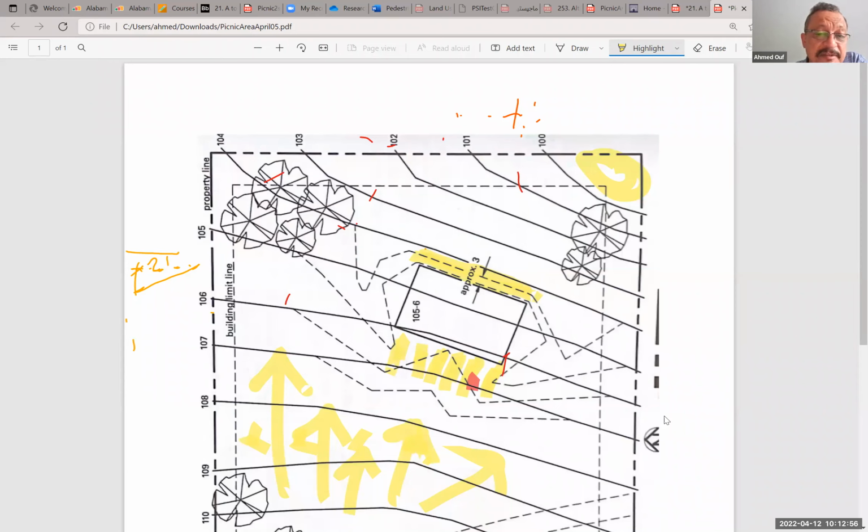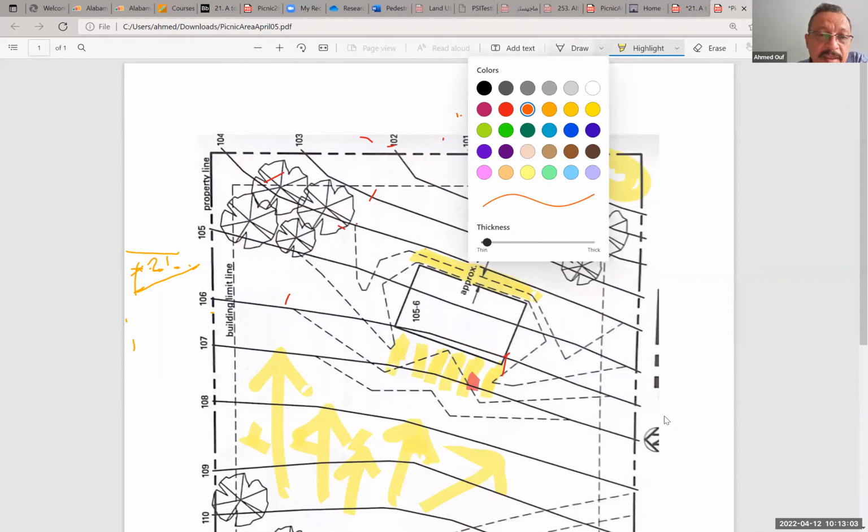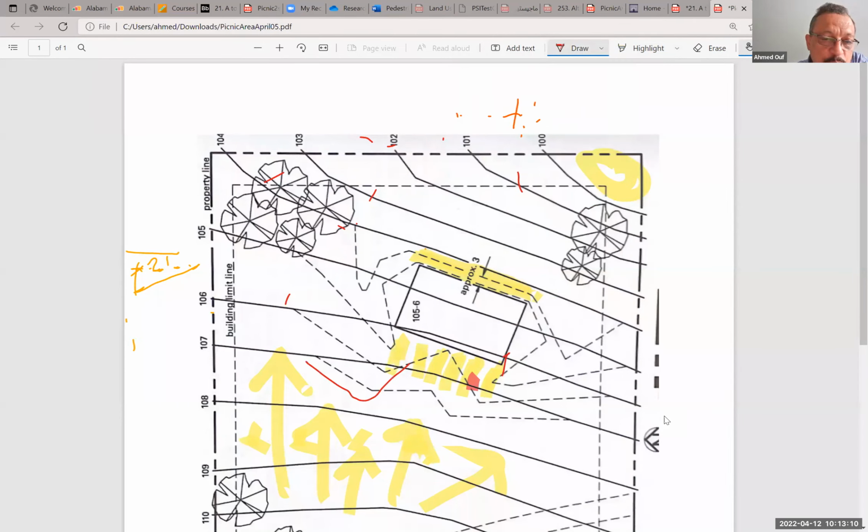I also have a safety issue in the back of the building, because when I'm reimagining the grading lines, like with these here, what's happening is I'm creating a swale. A swale is a lower area on the site where water can just go through. So instead of going to the building, I'm stopping that, and I'm attracting the water to go in that direction. And I will do the same on the other side, something like that.